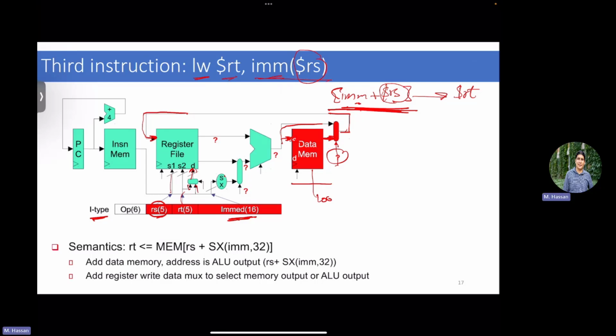Oh, that's a good question. If your opcode is 6 bits, it doesn't mean that you cannot have multiple logic layers on top of it, right? For example, this selection line is going to operate the same way whether you have a load or an add-I, or other types of immediate instructions. So there must be a logic layer between the opcode and the selection line.